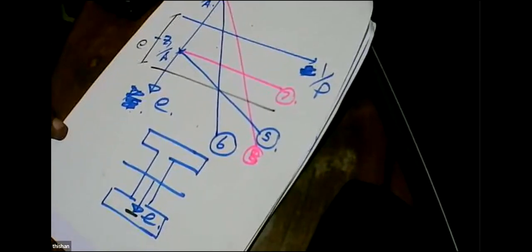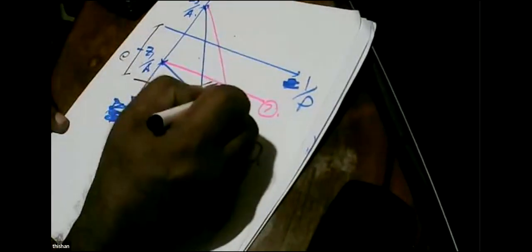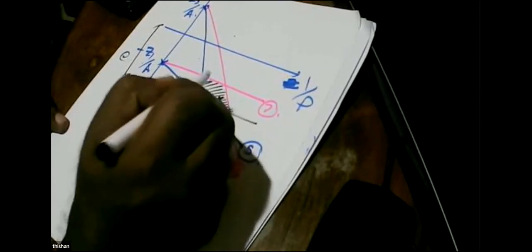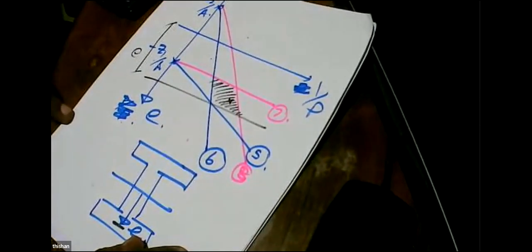So there's a maximum limit we can go. So once you do all that, we get this region. So the moment you select a point inside, you don't have to check stresses, because all 4 inequalities are satisfied by any point inside this shaded portion. So you don't have to do anything. You can just select and you don't have to even check the stresses.